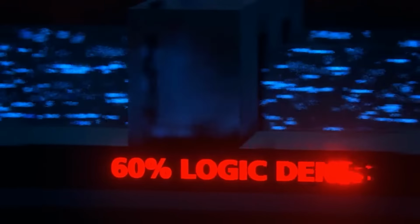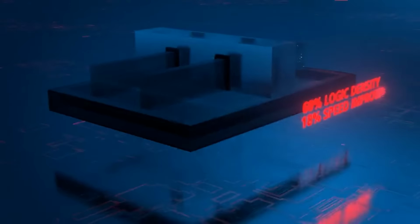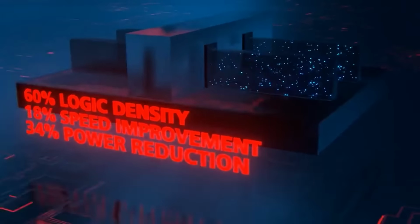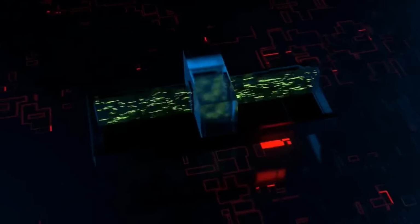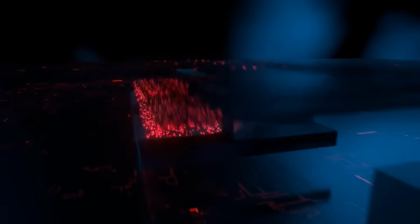But it's not all sunshine. Placing alternating rows with different fin counts increases design complexity. You have to make sure that very important logic gates and so-called critical paths are not placed in the rows with the lower fin count, where they would suffer from reduced performance. Instead, it's important to use the alternating rows in such a way that less important cells are placed on rows with lower fin counts, while important cells can benefit from the rows with more fins.